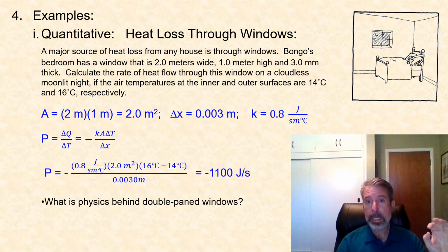If the window casing could get totally evacuated, then there could be no possibility of heat loss via thermal conduction, because remember that conduction requires a medium. So one of the ideas is, if you can partially evacuate that window to remove most of the matter, now you're really lowering the rate of heat loss due to thermal conduction. You're making the thermal conductivity constant very, very small.